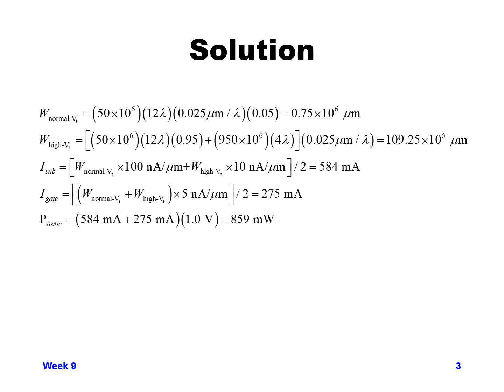Now let's go through the solution to our static power example. So first we want to look at what is the total nominal or normal VT width of transistors and what is the total width of high VT transistors. We'll begin with the normal VT.